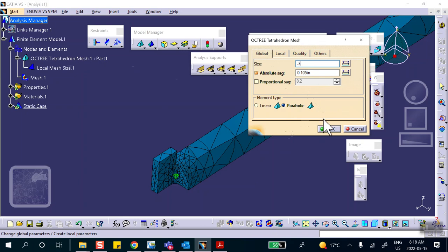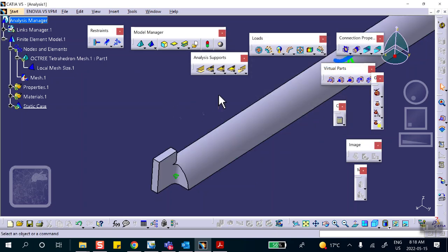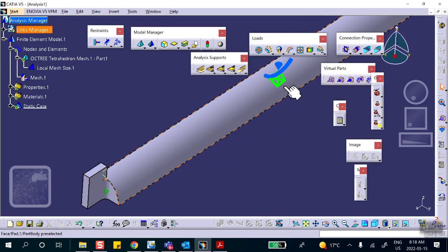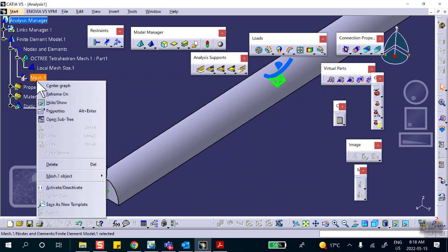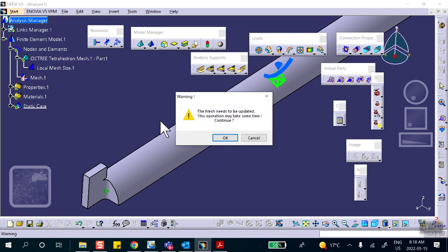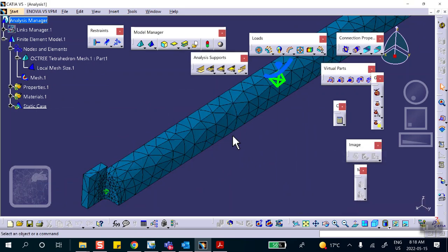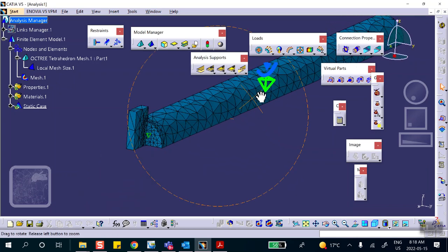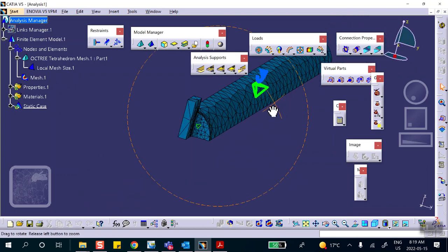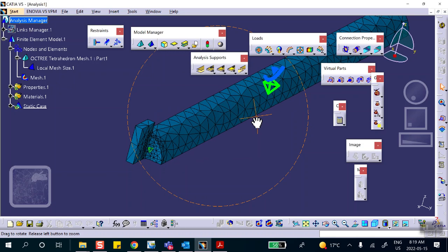The other one, the local mesh refinement, I'm going to leave the same. So you see, instead of that big size, at least it's a bit more respectable. So we go and activate this again. See, it's more respectable. Even if it's bothering you more, you can make that smaller, but that's okay. We don't need finer meshing around the hole, etc.